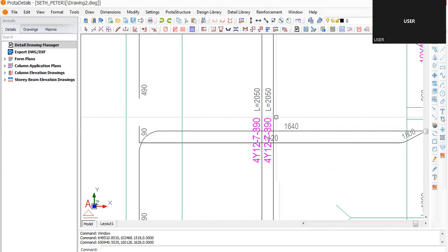So when you have two different reinforcements, but they are of the same size, let's say they are both Y12, and then they are of the same shape, and they are also of the same length, that is done when you want to come up with your bar bending schedule. So you can see that is how to actually come up with your schedule.